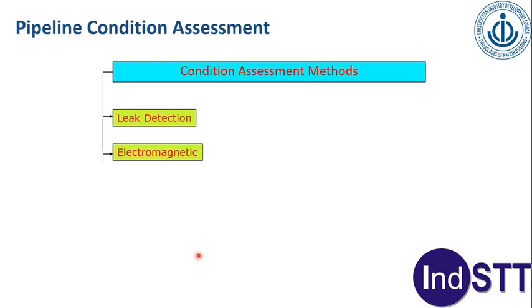Once we talk of leak detection, there are different methods: acoustic, sonic, hydraulic. So there are various methods available for leak detection. Then electromagnetic methods for condition assessment, which include GPR, EM, cable detector, eddy currents. Then we have physical methods which include smoke testing, dye testing, impulse hammer.